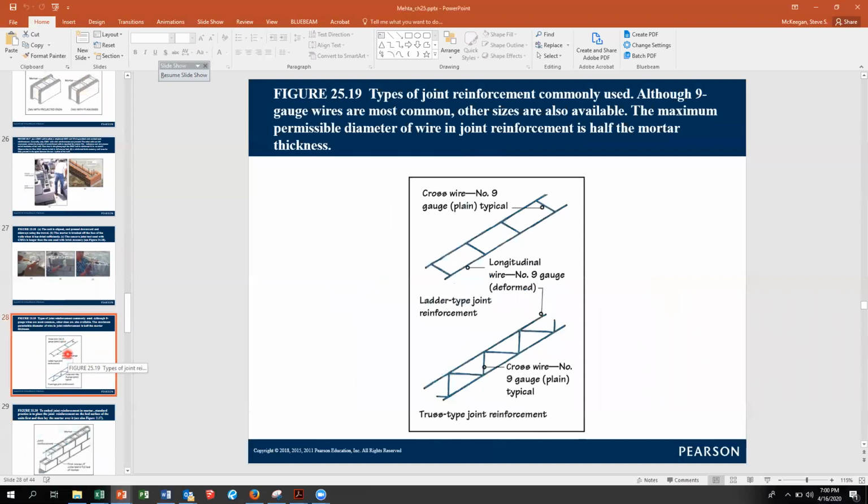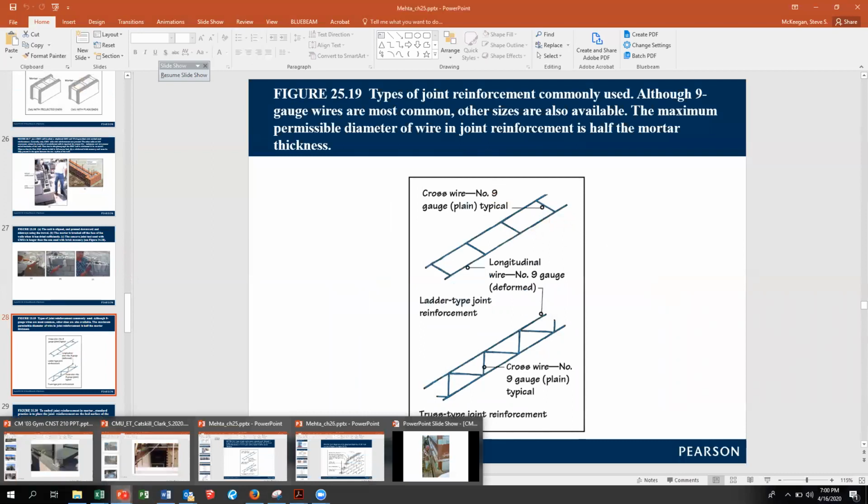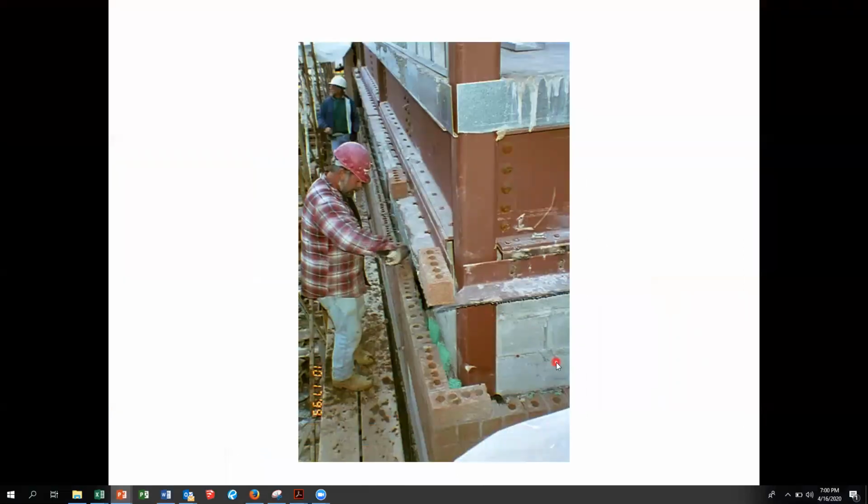So this is the joint reinforcement. Imagine that on the end of this wire are two eyelets that will bridge from the face of the block to the middle of the brick, and they become the brick ties. There's a strap that hooks into these two eyelets, and the strap is mudded into the bed joint of the brick as it gets up to this level.